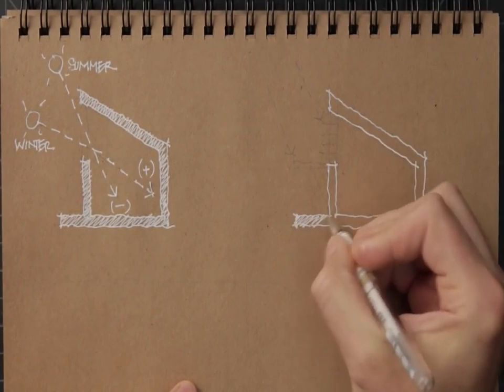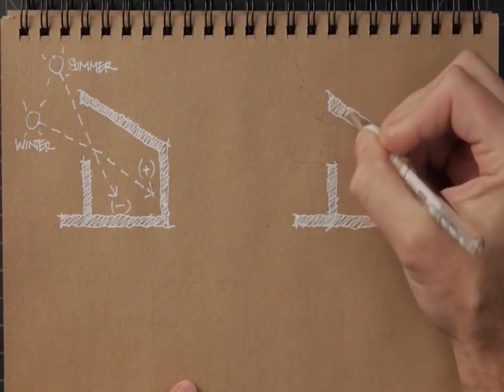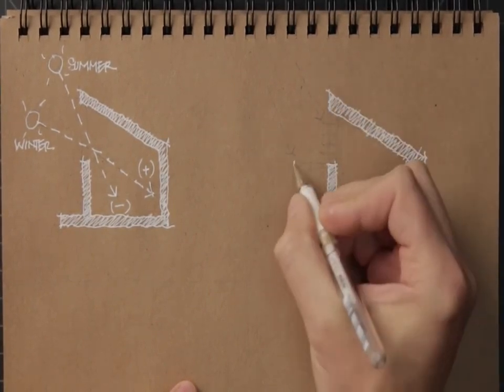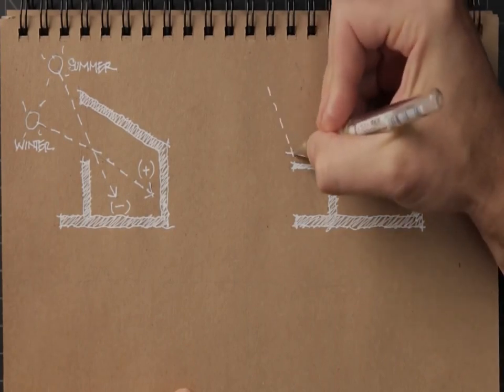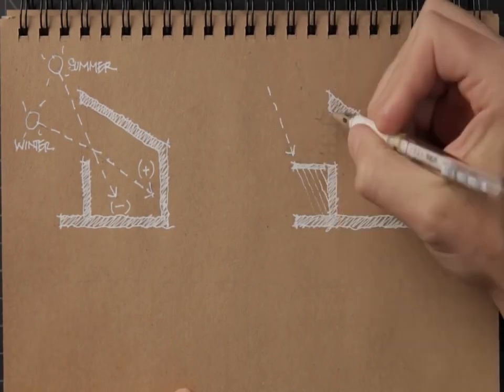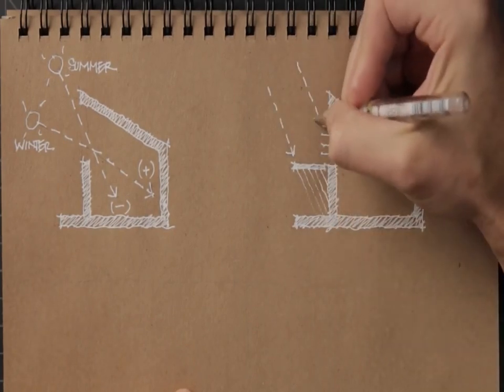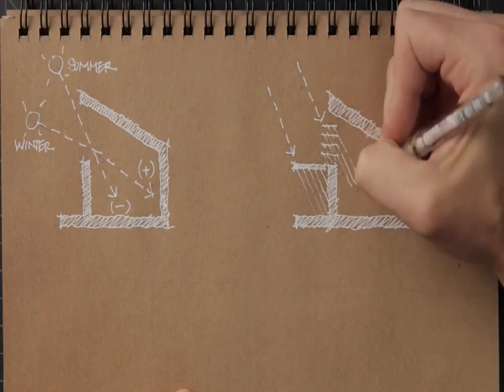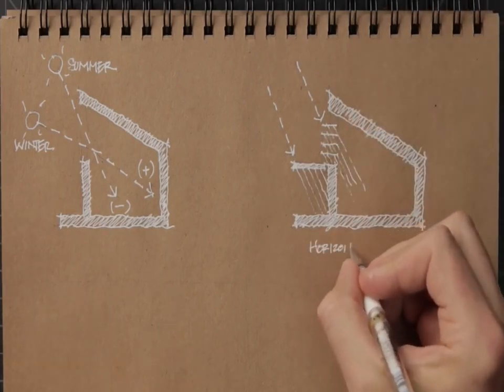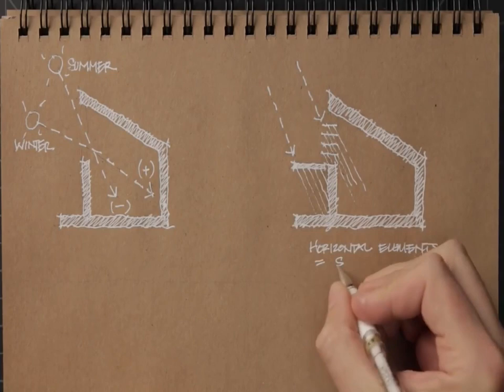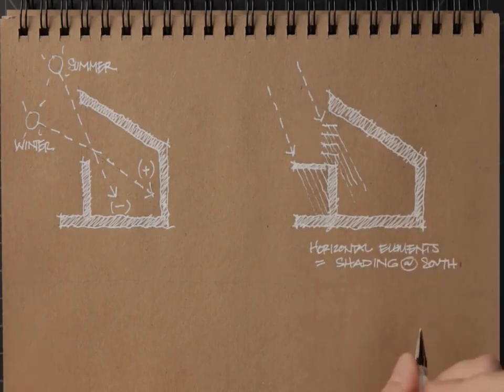To control the light and heat on southern exposures, you'll predominantly want to be considering horizontal elements for screening. That's because the sun moves from a low altitude in the winter to a high one in the summer. Horizontal objects act like the brim of a hat to shade the building, and it's the high angle sun that presents the most danger for overheating. While the low angle sun is good for us here in a cold climate, we want to let in the winter sun and use it to offset our heating costs.